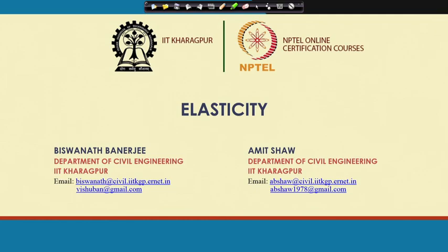We started with the definition that we had in our school days, that stress is equal to force by area. But then we discussed we have to look beyond this definition, because now we are not dealing with just one area or one force; there are different areas, different planes and different forces. So, there are different components of stress. We also discussed that stress is a point-wise description of the response of a body.